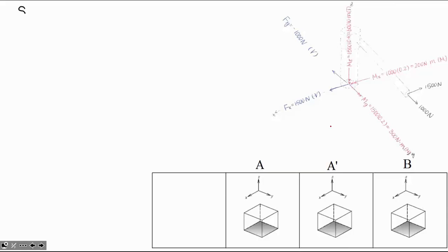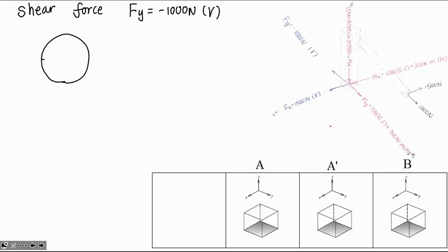We'll try to deal with another shear force, which will be the force in the y direction, negative y direction. So again, the steps to do this is also draw the cross-sectional area, and then try to draw the force. So this time we are going to draw the force in the negative y direction, which means we will know the neutral axis will be x-axis.